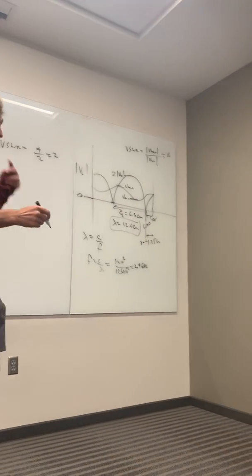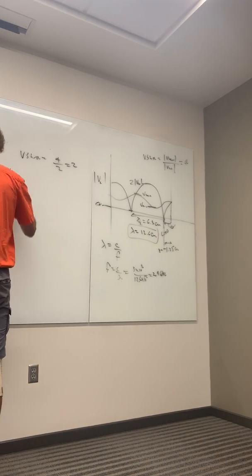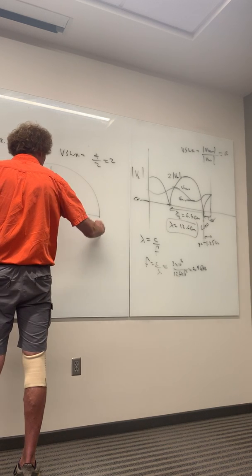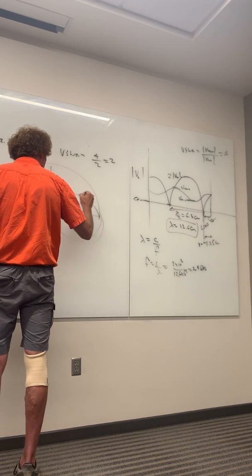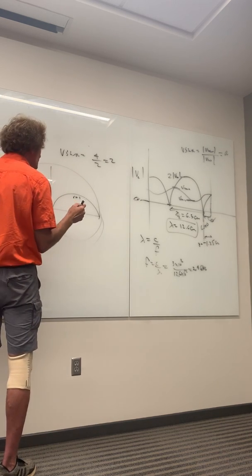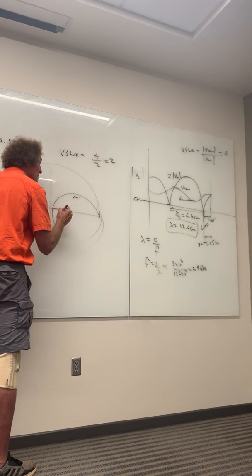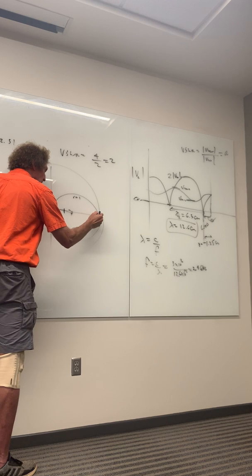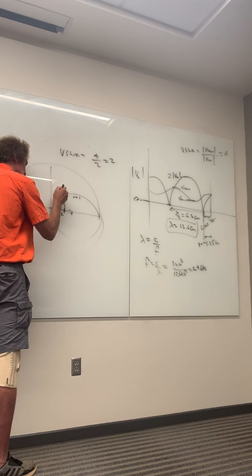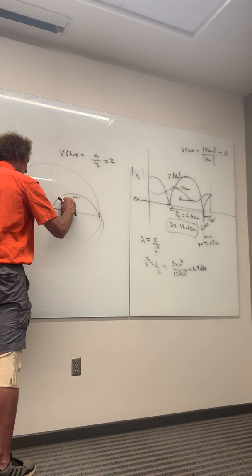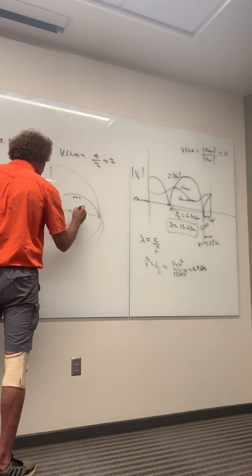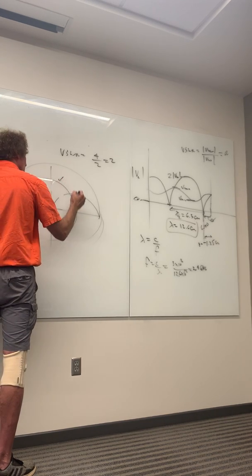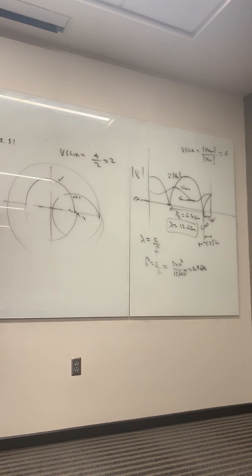Well, then that tells me everything I need to know, because now when I go to a Smith chart, and I have a VSWR of 2, that means I know the radius of the circle. And that's going to be right here at 2. Actually, it's a little closer, it's about here. So this is going to be 2, and that means this is what your circle should be. Redraw that a little. It's probably more like this. And this is a VSWR of 2 right there, right?